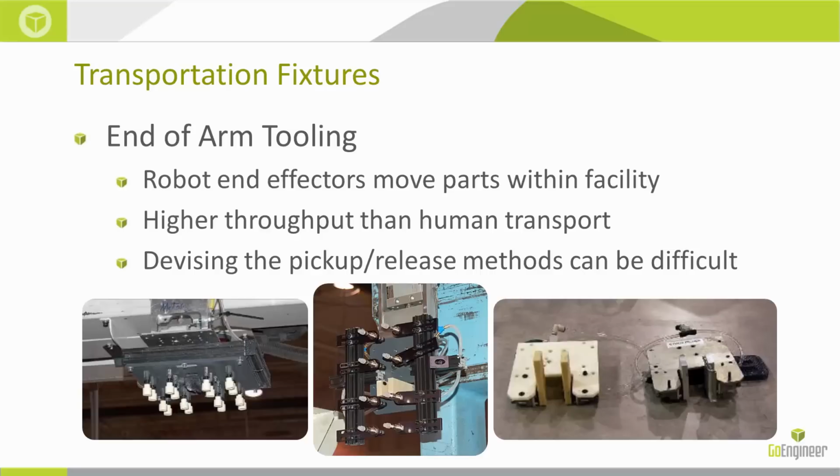Nice thing about plastic tooling on the end of a robot instead of metal tooling is that plastic gives, plastic breaks. There's no shock load for the robot, no destroying the encoders or having to get them recalibrated and whatnot. So I like the plastic end effectors, end of arm tooling a lot.